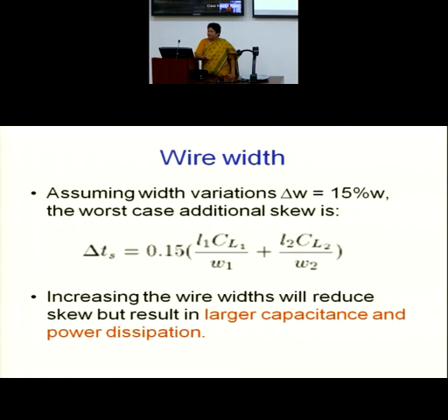But even when you are inserting a ground rail, the wires are becoming apart. You are increasing the distance between the wires. The only strategy which is good enough is to split the wires apart to reduce the crosstalk. But sometimes it is not possible to have them too far apart. Then bring them together and place a ground rail in between so that you can reduce the mutual coupling, because crosstalk is because of mutual coupling between the two conductors. Inductive and capacitive effects come into the picture.